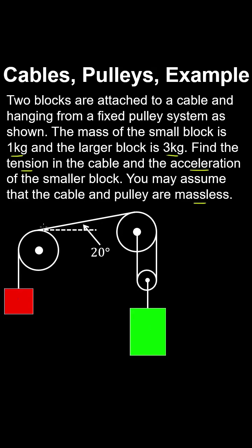So if you just follow the cable which is wrapped around these pulleys, you'll be able to draw the tensile force at certain locations. Think of this like we're taking the free body of each component of the cable pulley system. And therefore the force in this cable is 2Ft, which is the same as the force acting on the block. And if we're taking free bodies of the block, the smaller block is expected to accelerate upwards.